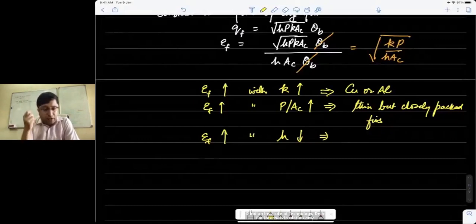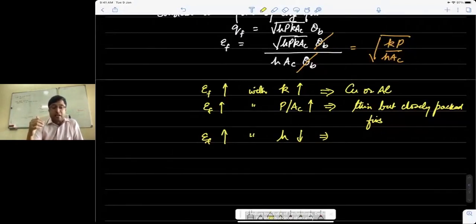heat transfer coefficients for gas, for liquids, both in natural and in forced convection, I said h is much smaller in free convection, and also it's much smaller in gases. So it makes more sense to put fins when you're dealing with the gas side instead of the liquid side. If you look at the car radiator, these fins are put on the outer surface where heat exchange has to be to the surrounding air.